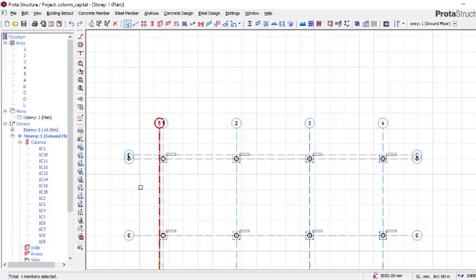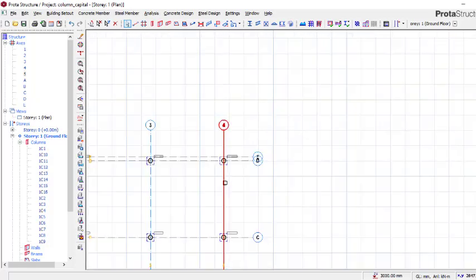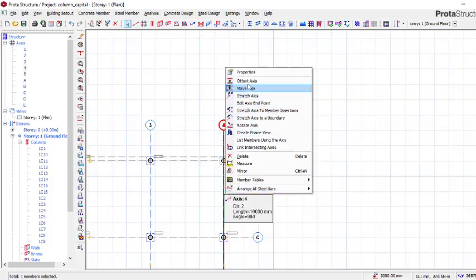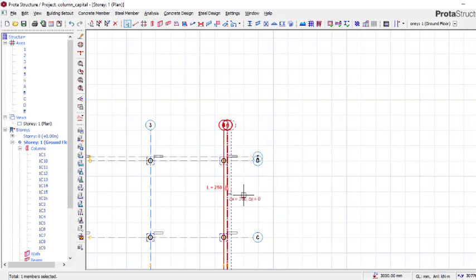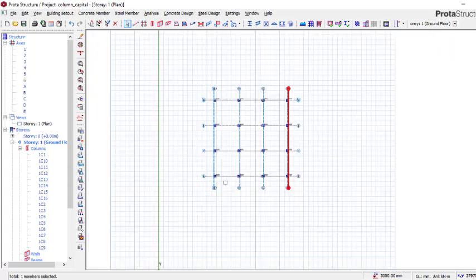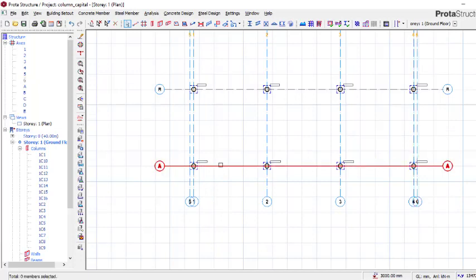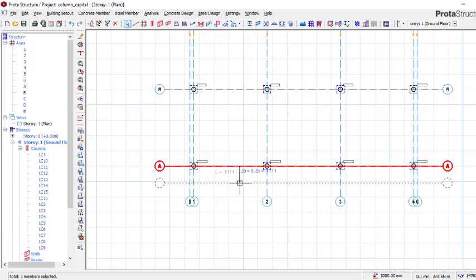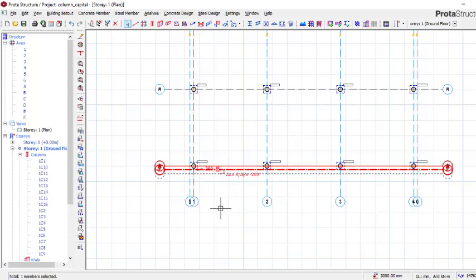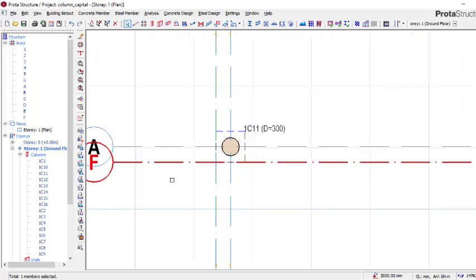You can escape. Then at this side I will right click, offset to this side, just drag your mouse to that side, then this is positive 250, enter. Then at this side I will offset downward. Drag your mouse downward. You don't even need to drag it downward, in as much as you know the negative and the positive side. So 250. All right, so that is good.